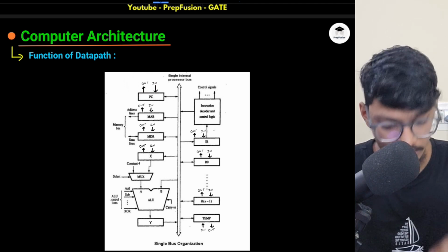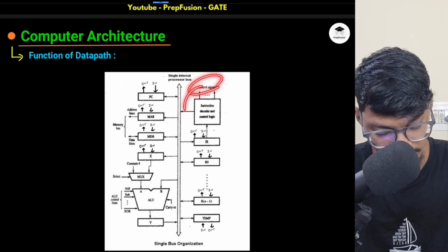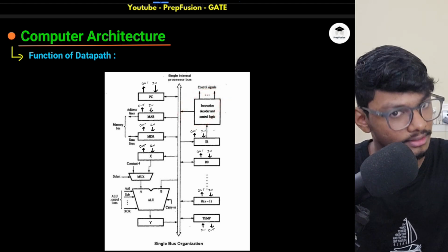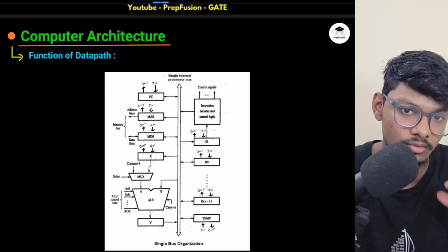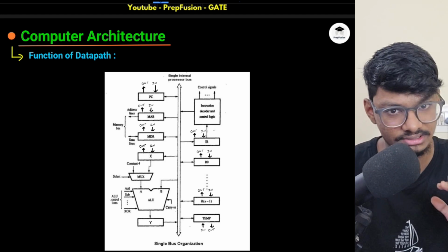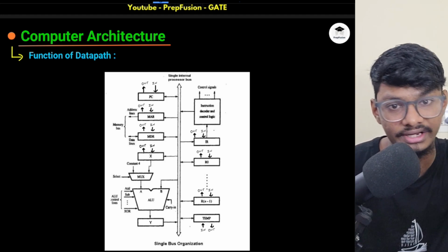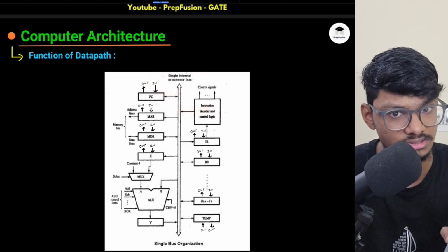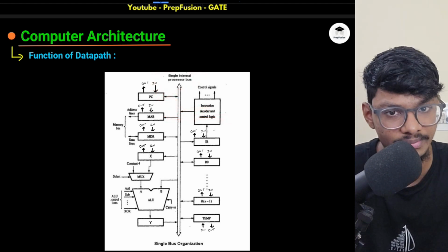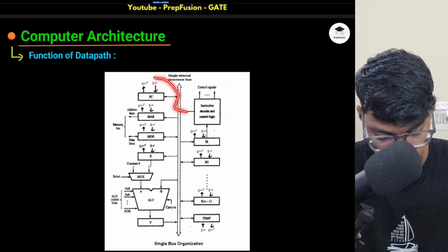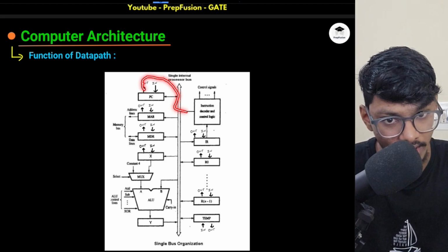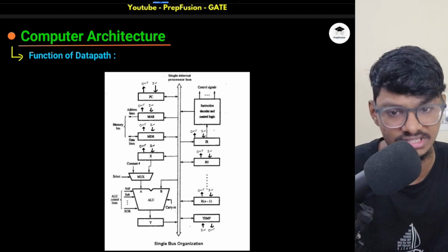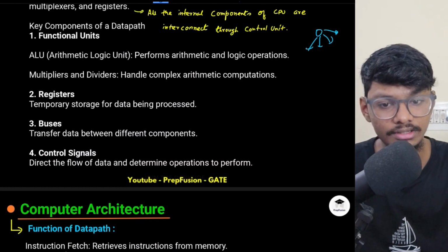Okay. So I hope you understood how my instruction decoder sends control signals. How does it decode? We'll come to that later on. First of all, let's just understand that the control unit has decoded the instruction, and it knows that I have to read from the PC. If it has to read from the PC, it will send some signal through this common bus to the PC that, hey man, I have made my out signal 1, so please give my PC value. So that is what my control unit does.